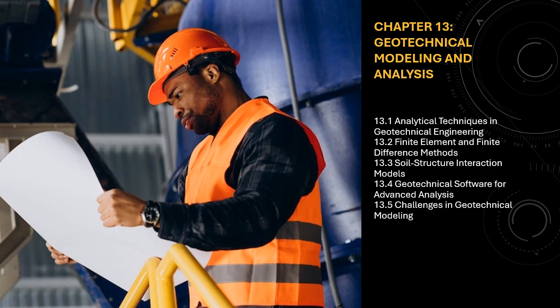13.1.1.3 Slope stability analysis. Closed-form solutions, like the limit equilibrium method, provide a way to assess the safety factor of slopes by considering forces acting on potential failure surfaces. Classic methods such as Bishop's method or the Janbu method rely on simplifying assumptions regarding the geometry of the failure surface and the shear strength of the soil.